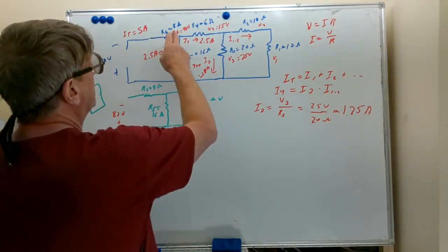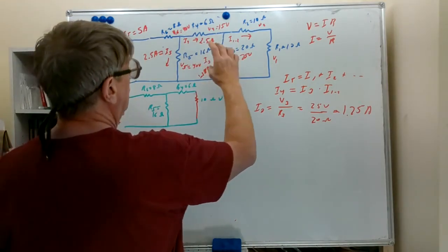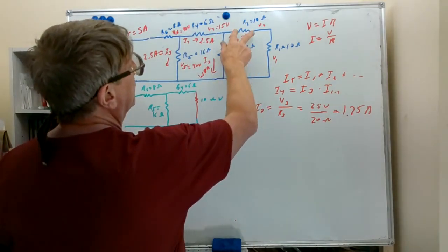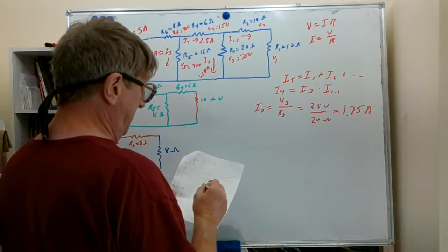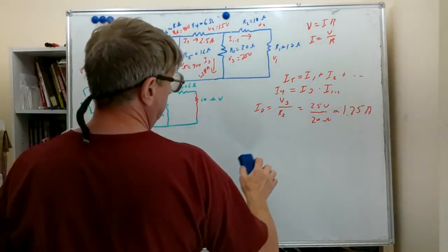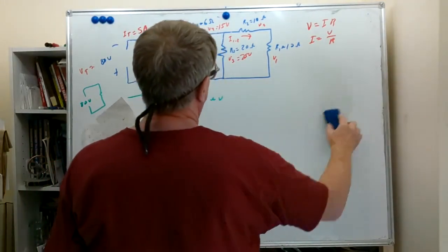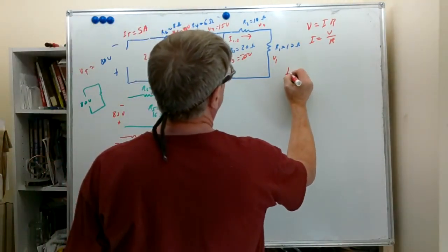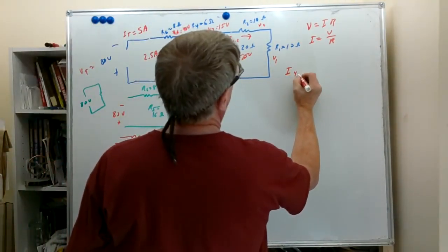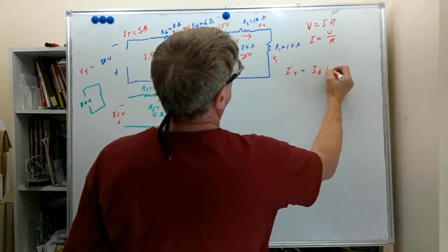So we've got voltage here, we got voltage here, we got voltage here, we've got voltage here. We don't know voltage here or here or current through here. So we're getting pretty close to being done with this problem, aren't we? So let's use our current divider formula with some different subscripts now. It's basically the same one, but we know more values. I4 equals I3 plus I12.